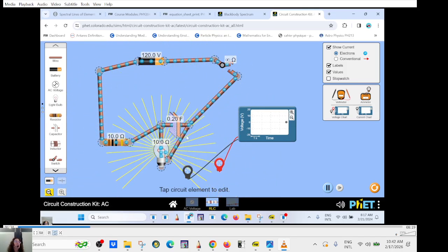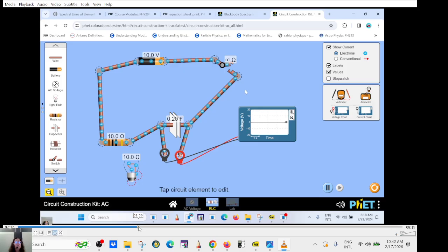So you're going to have a flash. The smaller the resistance, the smaller the time. And then it takes forever to get rid of everything. Now, I'm going to close the switch. It's charging, charging, charging. It's going to get to 10 volt. And now it's charged. There is no more current.